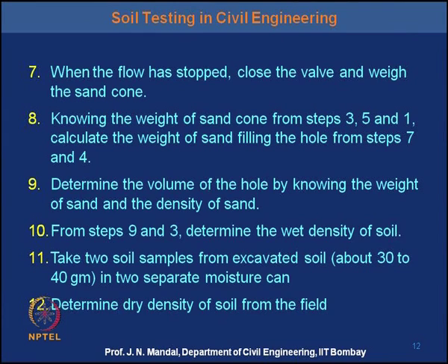Knowing the weight of the sand cone from steps 3, 5 and 1, calculate the weight of the sand filling the hole from steps 7 and 4. Determine the volume of the hole by knowing the weight of the sand and the density of the sand. So, you know the weight of the sand, so you can determine the volume of the hole. From steps 9 and 3, determine the wet density of the soil.